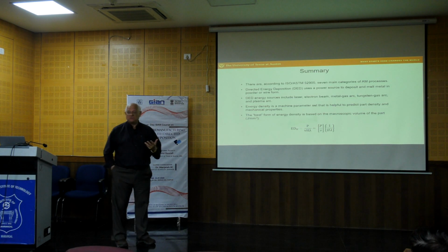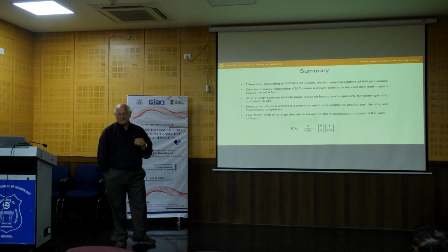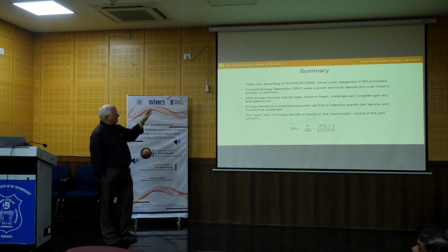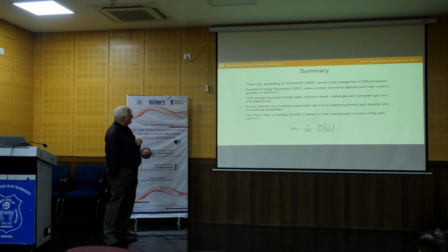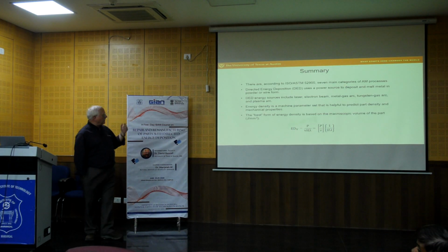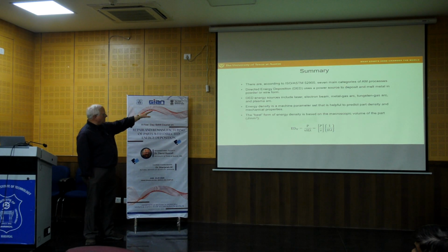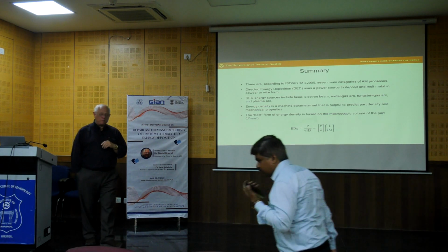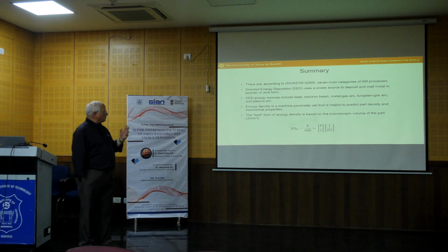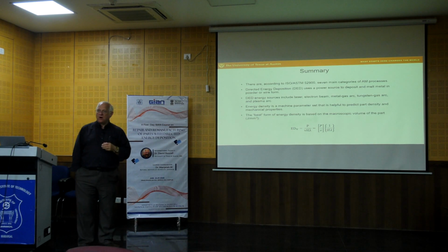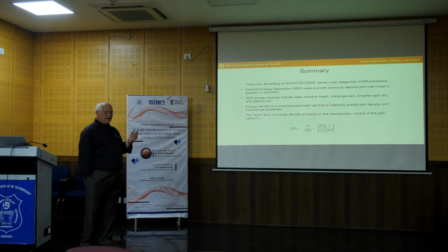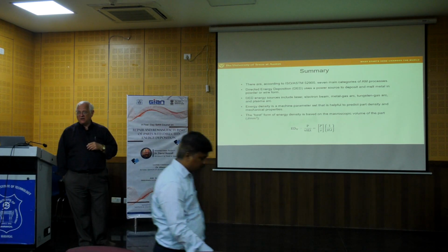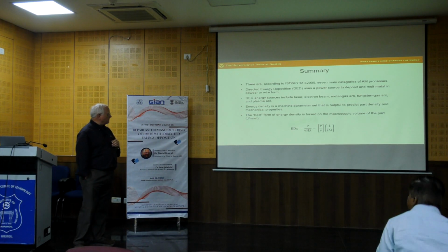But anyway, the committee is very active. We continue to look at technologies and evaluate them. So directed energy deposition: we have a power source to deposit and melt the metal in powder or wire form. We talked about some of the advantages and disadvantages. We talked about the energy sources and that the energy density really is a key parameter to help predict part density and mechanical properties. And again, the energy density approach was really developed for DED, that was its emphasis.